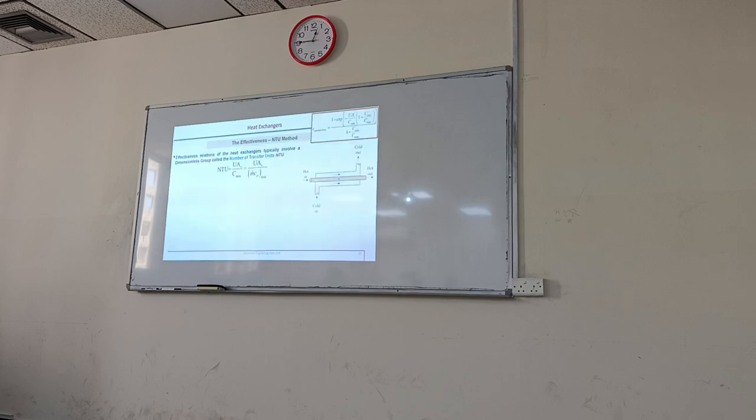Similarly, here now he is defining these terms. They are naming it as NTU. Now look here in NTU, the MCP product is normally fixed for a particular heat exchanger. U also gets fixed. So it is all dependent upon area. Increasing the area will increase the effectiveness.